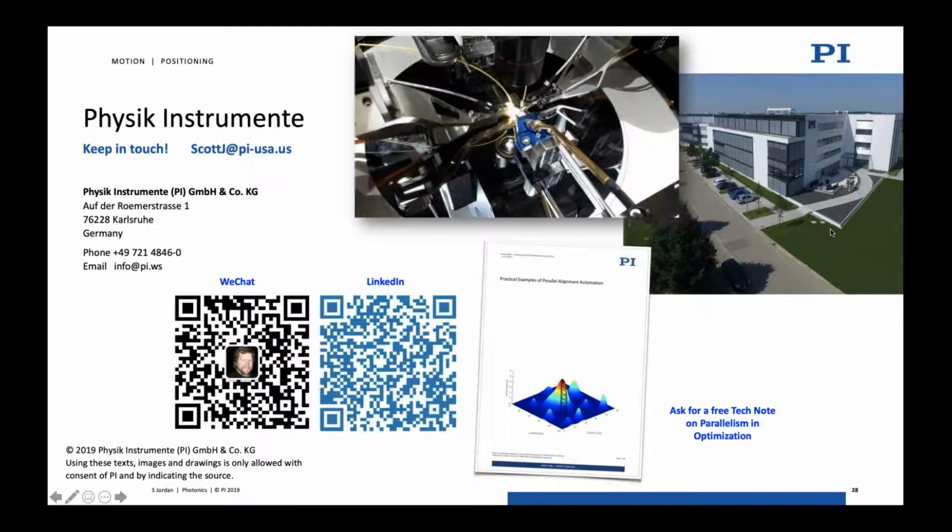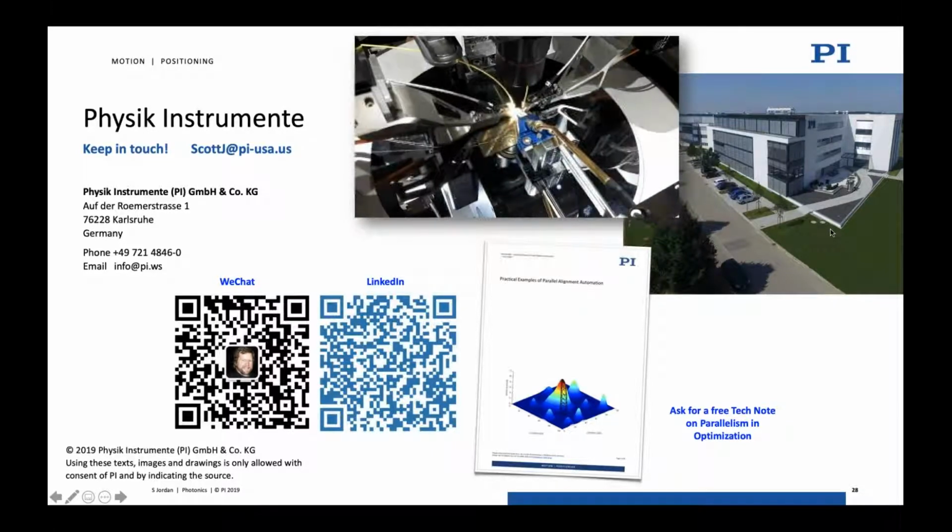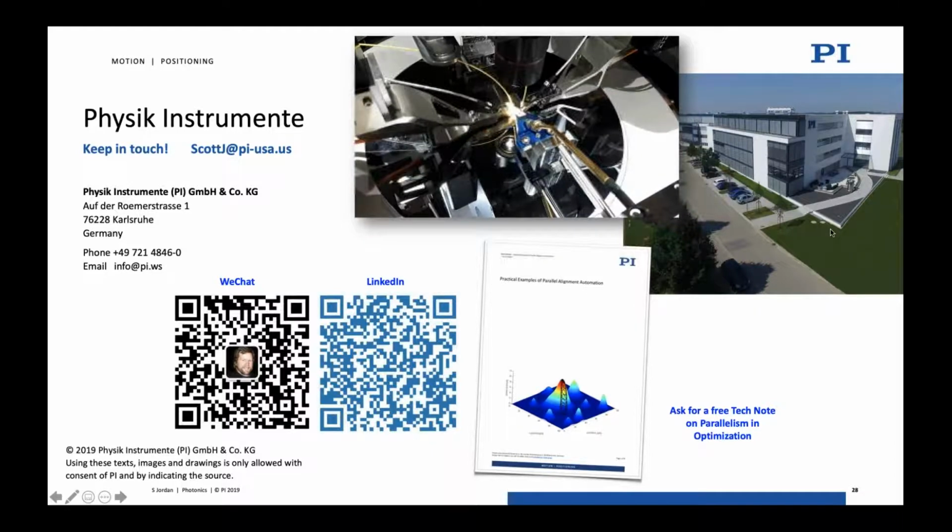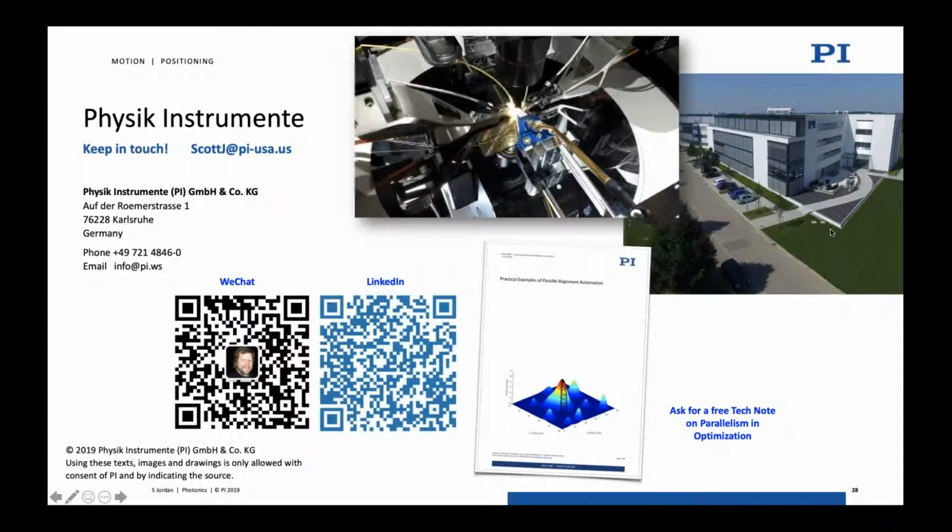Typical resonant frequency of a nanocube with a typical load is in the order of several hundred hertz, which means the positioning bandwidth is typically, rule of thumb, about 1/3 of that. So if we have a 500, 600 hertz nanocube, that means we can do these little circular dithers well over 100 hertz. That's fast, especially by alignment standards.